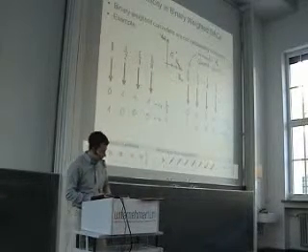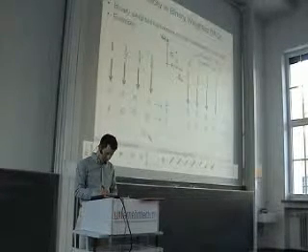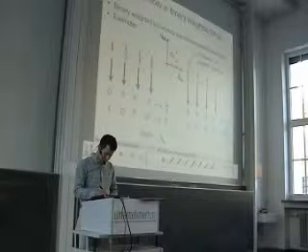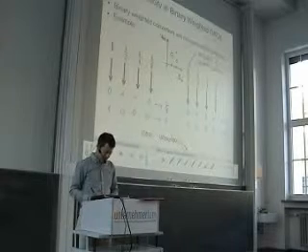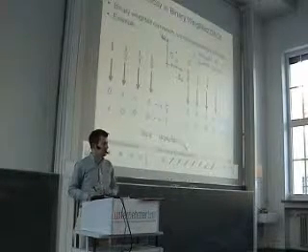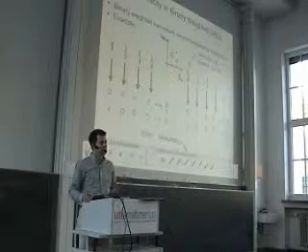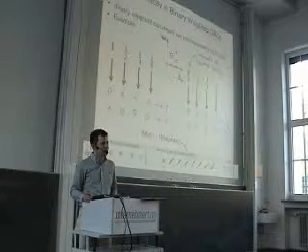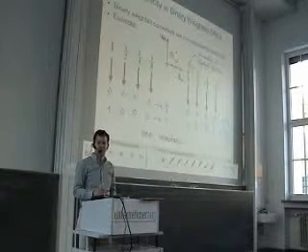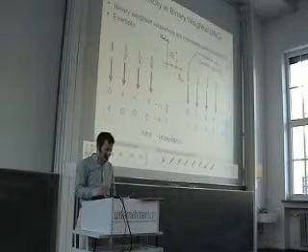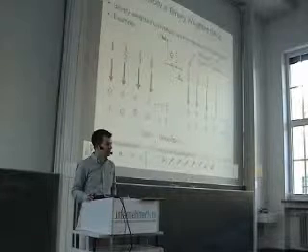So this is non-monotonic behavior. Which means if there is a mismatch due to variation, then we can end up in a situation that this device is not monotonic. Well, here of course it's an extreme case that this happens in the MSB is very unlikely. However, this is an easy example to illustrate what can happen here. Okay?